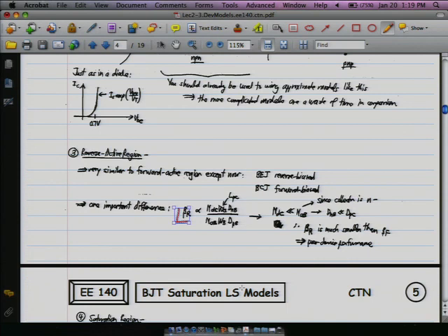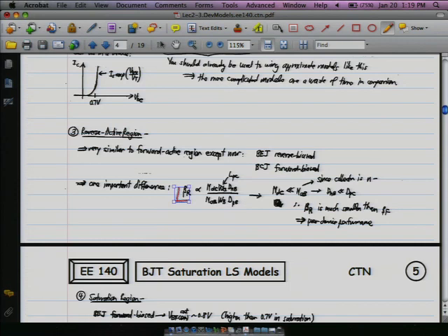And what it comes out to, the important thing, is that because the various regions are doped as they are, because here the base is doped fairly heavily relative to the collector, we don't end up getting much gain out of it in the reverse mode. So I'm just going to go on since that region's not all that interesting. Basically, you just get horrible device performance out of it.